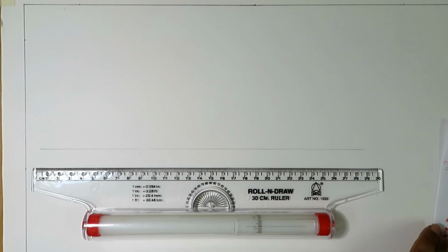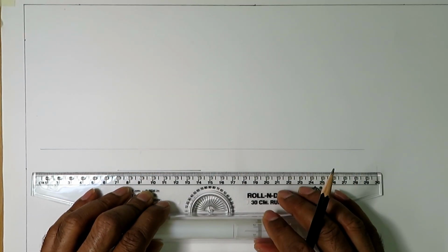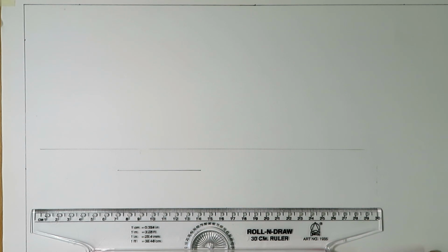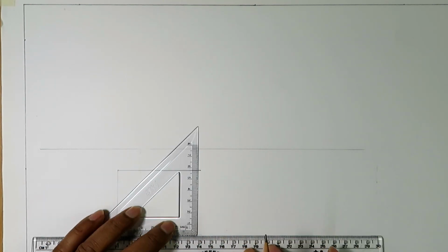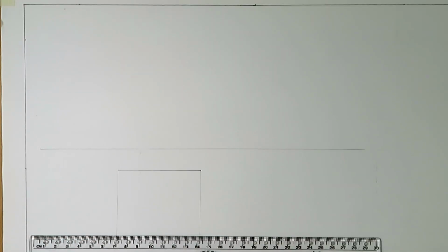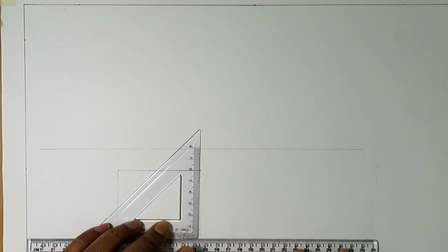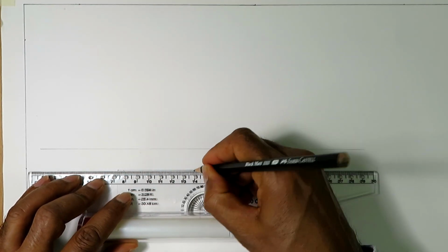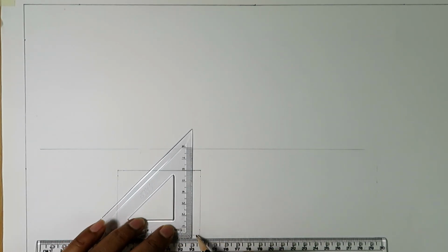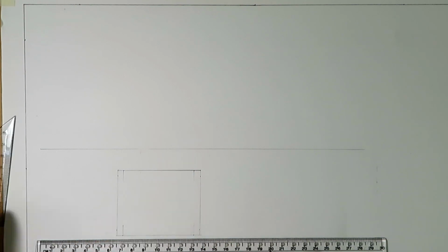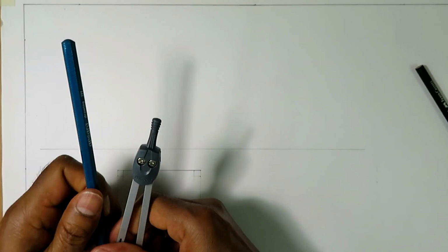Since this drawing will take a lot of time, I have made the video very fast, and you can see the entire process of drawing that I have followed. But always remember, for all dimensions I have used, the actual dimension has been divided by 5 to obtain the dimension on the drawing sheet. And the main objective here is to see whether our decision of 1:5 scale was correct or not. So this is the top view.